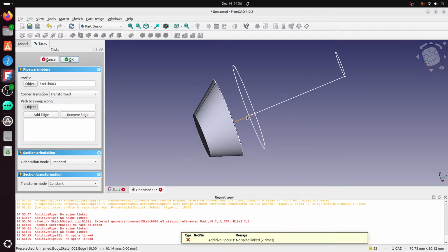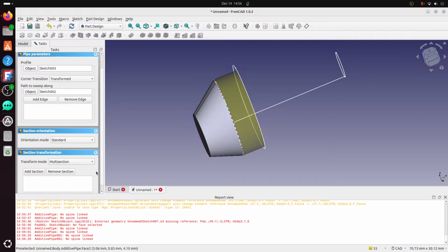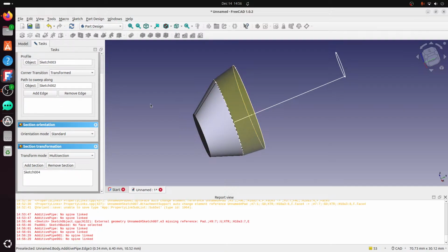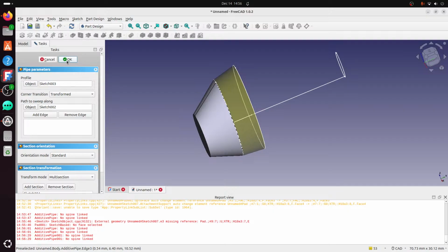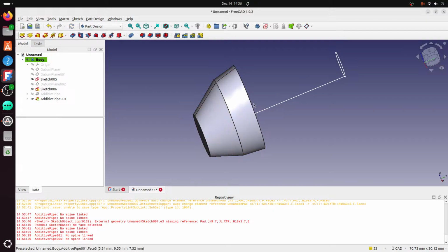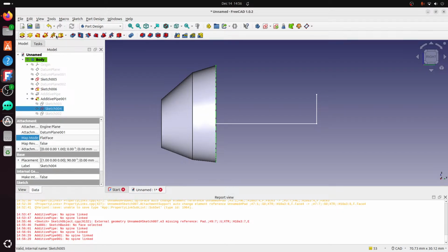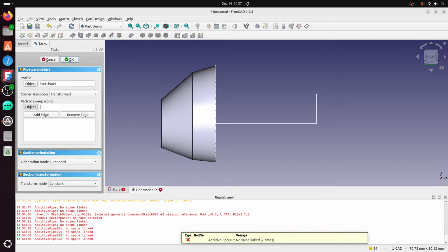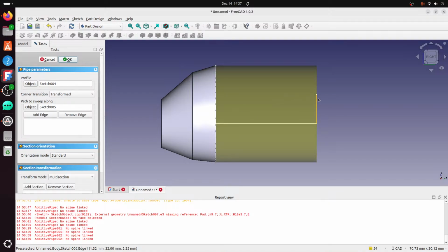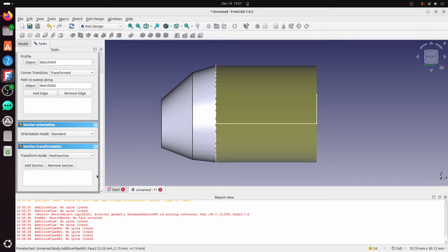And then when I get the body profile built the way I want it to, I'm going to scale it down to like 3/4 of the outside shell, and then I'm going to subtract the inside shell that's smaller from the outside shell, and that'll make the whole thing hollow.